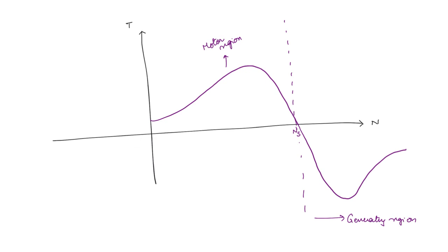Now what will happen if the speed becomes negative? Negative in the sense it is moving backward with respect to the magnetic field. So in this case we call this the braking region. Why do we call it the braking region? The induced torque will still be positive. That means it will try to reverse the rotation. This is a negative speed, right? But induced torque is still acting in the positive speed direction. That is why this region is called the braking region.